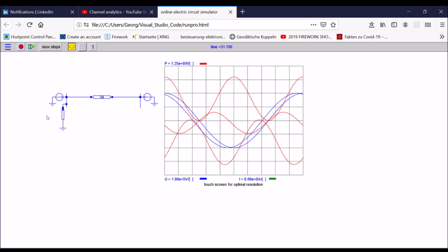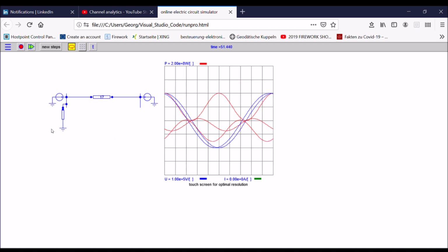So this applies really for real power. The torque supplies real power. Please note that there seems to be also something like a reactive power in the system here. How can that be? Because I have only a real load. So the reactive power is coming from this line here. So the line has a reactance, and therefore you will always see in such a system also somewhere reactive power.